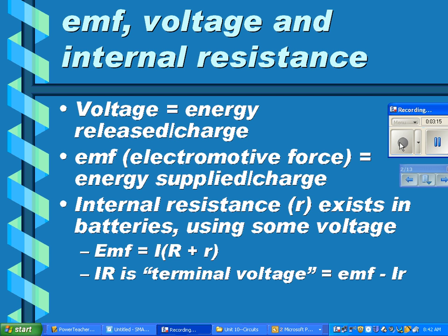So sometimes you'll hear this thing called terminal voltage, or what we talked about in the lab as being the applied voltage, or the voltage you measure in your circuit, or that you get at the terminals of the battery. That's equal to the EMF created by the battery minus the voltage used internally, which is the current times the internal resistance.